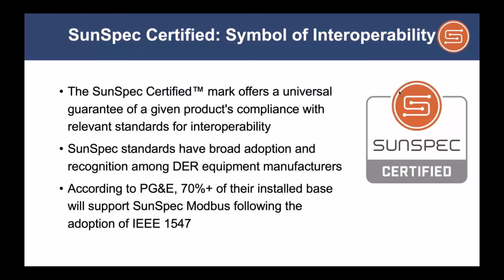With the SunSpec certified service, we are able to do a complete evaluation of all of the required protocols, including SunSpec Modbus and IEEE 2030.5. And with that, we confer a mark that we have done this type of certification. We put that information on a website that you'll see in a moment. And this is the guarantee that the product is compliant with the relevant standards.